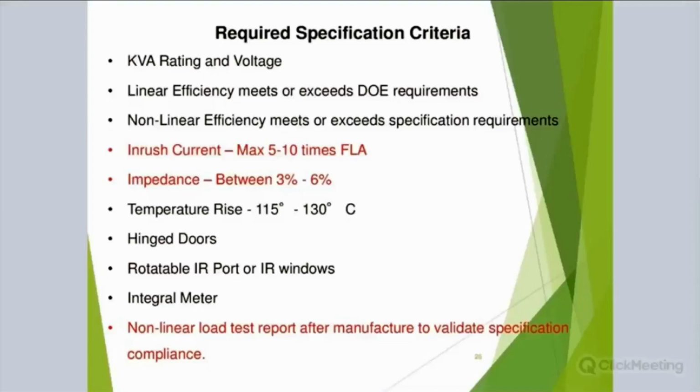The last, and this is probably one of my most important criteria, is the nonlinear load test of a transformer, to validate that they meet the spec. This is where you're telling the manufacturer or the supplier, I want that transformer tested before it ships to my facility, proving that it meets what I've specified. Now you as a customer know you're getting what you're paying for.